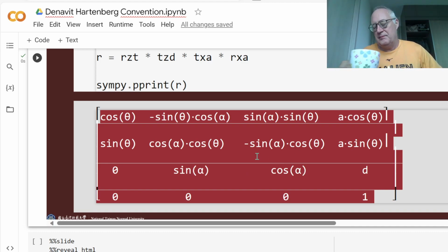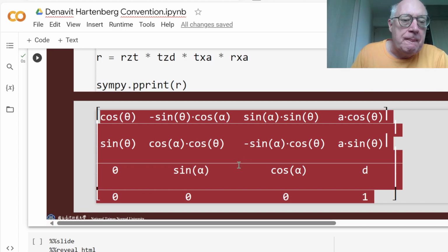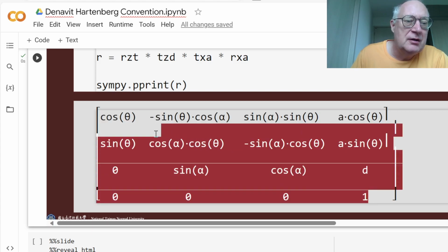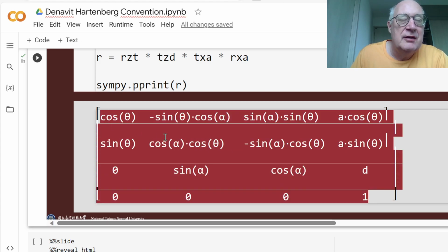I think nowadays computers are fast enough that pre-calculating this in this form is probably not really necessary. You can also compound the 3 matrices that are constant for each link and then just have one with respect to your joint variable, either theta or d.